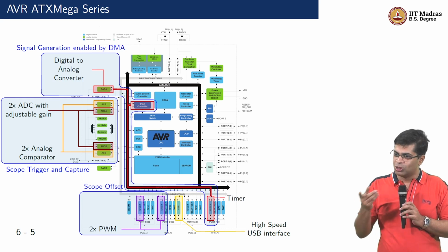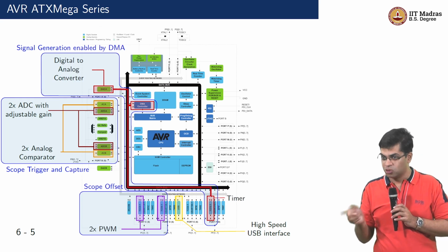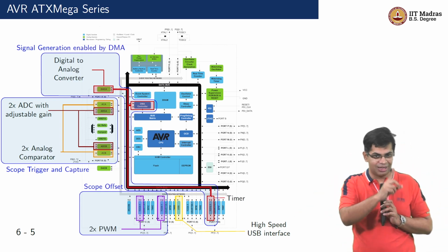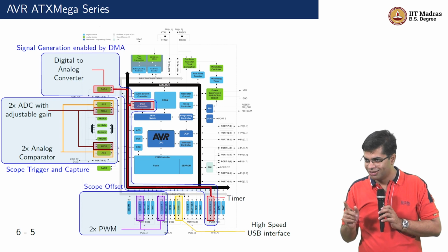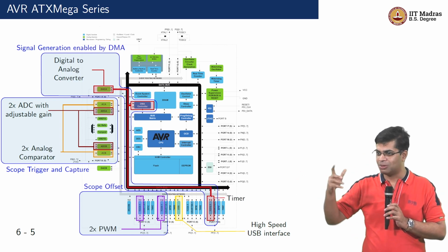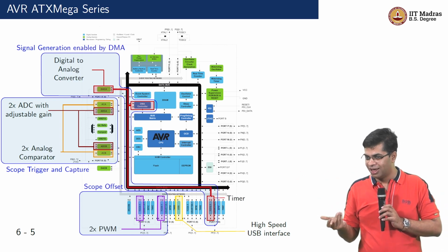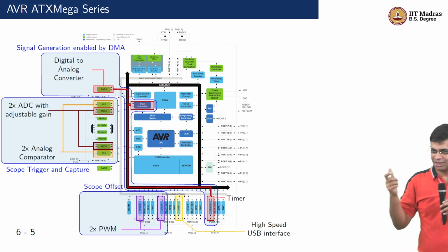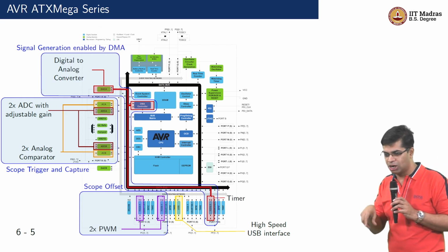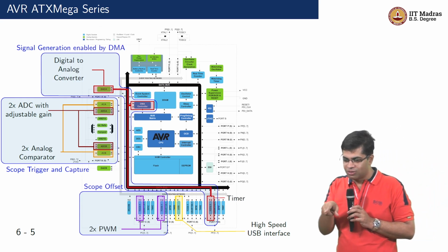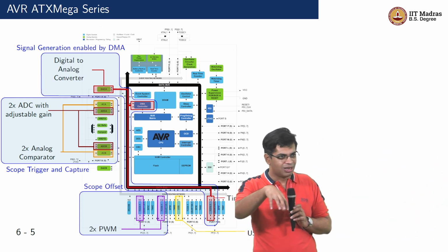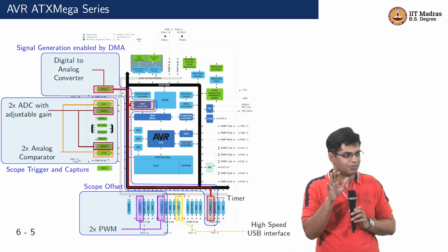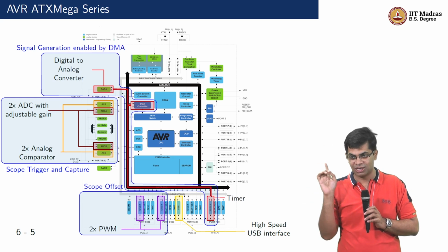It does not have the USB interface as well. If you just look at it, the TI chip is actually more expensive than the ATXmega chip, but it does not have some of those functionalities. And then we had to do a very clever use of the hardware which is available on your Arduino and what we have on the TI chip, with the programmable gain amplifier, to achieve what we wanted. All of this with a cost objective in mind.